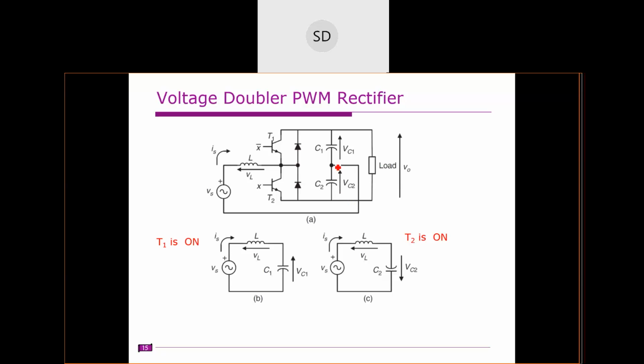Here too, the current is flowing inside either this upper capacitor or this bottom capacitor, so some disturbance in voltage will occur. Between these two capacitors, which are connected like this, if current is flowing inside and away from the circuit, then the capacitor voltage will be affected. We already discussed this in the case of the neutral point clamped, the diode clamped inverter.